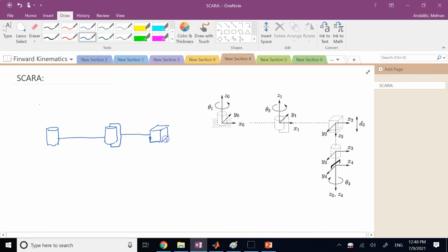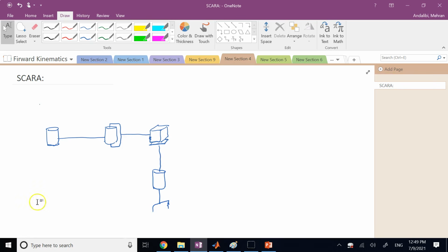So here you have this first rotary joint, the second rotary joint, now the prismatic, and the way I put this plane, the direction between these two planes tells me the direction of what? The direction of prismatic motion, which is up and down here. And finally, I have my final rotary joint here, which is another Z. And then attached to that, I can have my end effector in any direction that I want. Okay, so this is my SCARA with the end effector. There are 4 joint variables. And now I can get rid of this, okay? So we can practice the SCARA together.